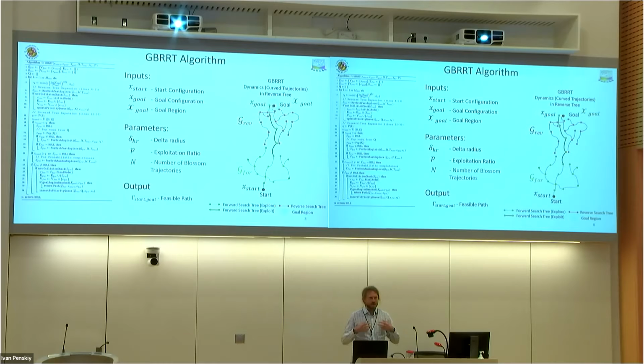And also these sampling-based motion planning algorithms usually have completeness guarantees in the form of probabilistic completeness, or essentially, as you sample more, the probability that you find a solution approaches 1 in the limit as the number of samples approaches infinity. But in order for that property to hold, we need some nice sampling over the space where we have a dense support for the sample distribution. And so we're going to alternate between these two things.